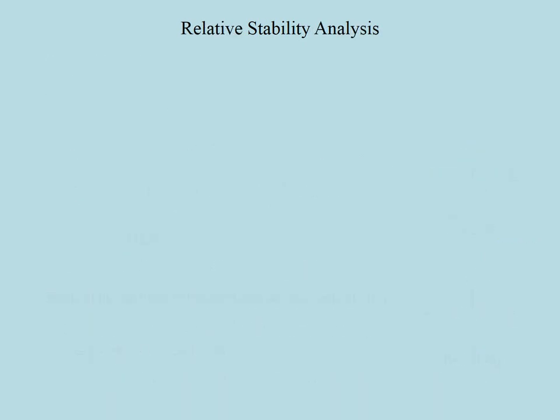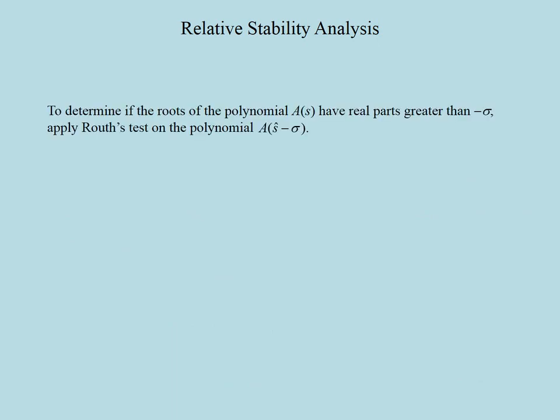Routh test can also be applied for relative stability analysis. That is, to determine if the roots of a polynomial have real parts greater than, say, minus sigma, we can redefine our frequency variable s and apply the test on the resulting polynomial.